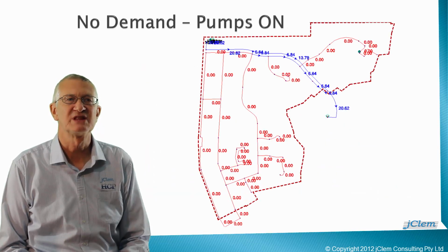Now shifting our thinking to the amplitude of pressure surges. Remember that the rate of velocity change governs the surge amplitude created. A pump stop scenario with no demand during a winter night will generate a velocity change from the pump's flow rate down to zero. The scale and rate of velocity change will depend solely on the pump's behaviour. Flow and velocity changes in some parts of a reticulation pipe network will be negligible throughout the entire pump stop event. Velocity changes will only occur in pipes carrying pump flow from source to its destination.